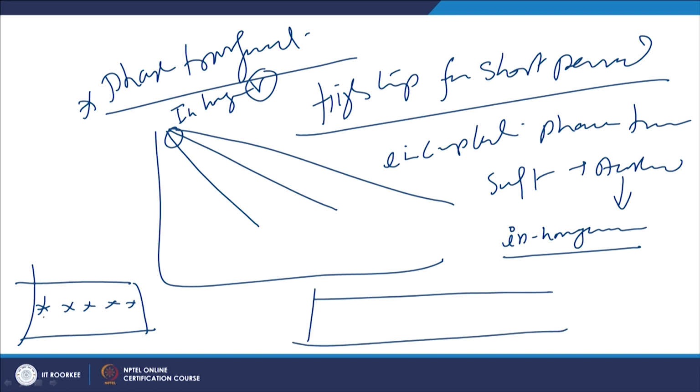If we just take the example of points 1, 2 and 3, the weld thermal cycle for point 1 will go like this, where very high cooling rate is observed and a higher peak temperature as far as the weld thermal cycle is concerned, time and temperature.